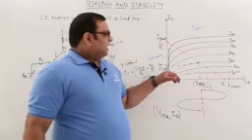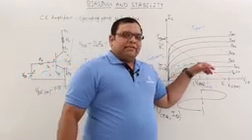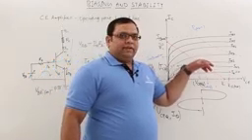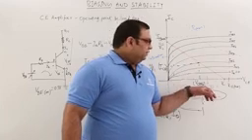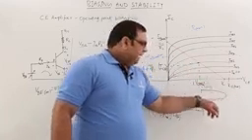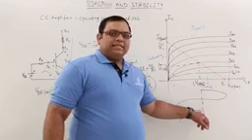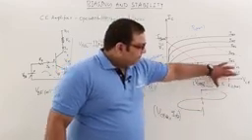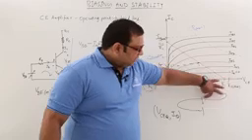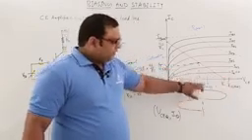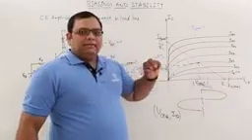So normally we keep the transistor in the active region only. We take it in the middle of the active region, so we normally take it in the middle of the load line. This will give maximum swing for the transistor. So observe, this is VCE I am drawing. VCE will have the highest swing sinusoidal waveform if you take it in the middle of the load line.